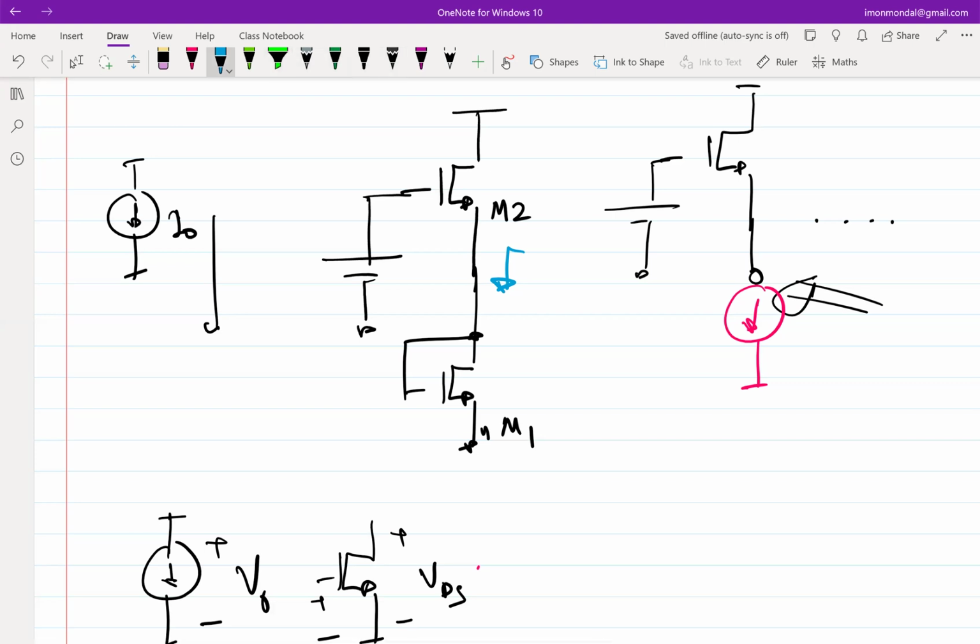So, what happens when this voltage increases? The condition on M1 tries to ensure that this current increases, because VGS increases. But the condition on M2 tries to decrease the current because the gate is constant, source is increasing. So there is an inherent feedback which will set the current, but the value of the current need not necessarily be equal to I0 that you intended, right? So this circuit has its applications, but not with regards to whatever we were trying to achieve.